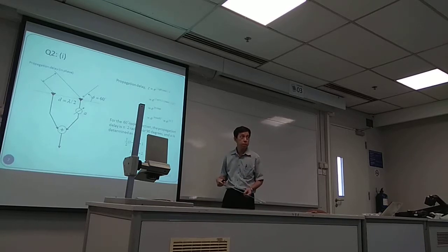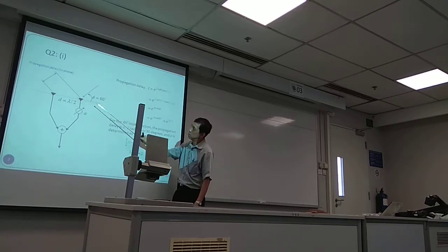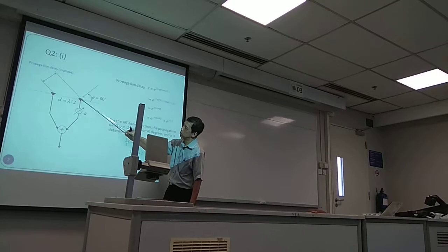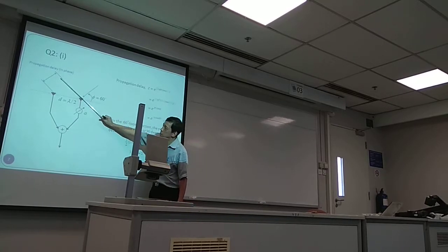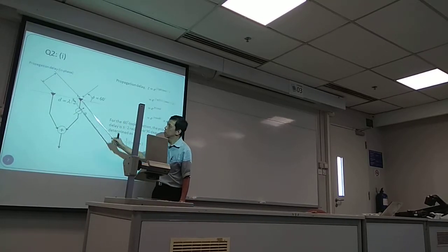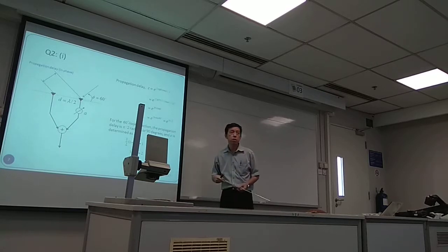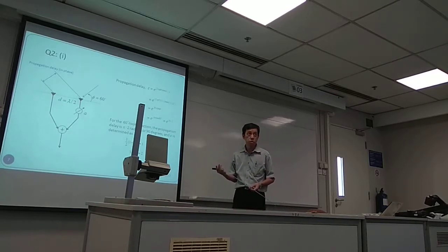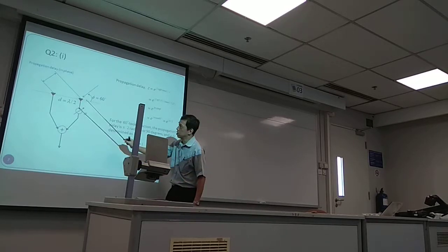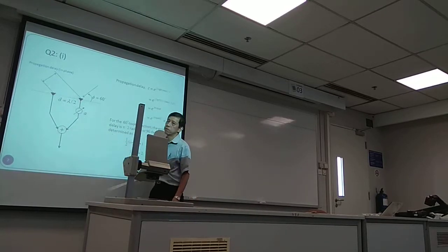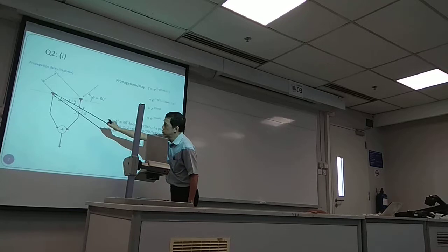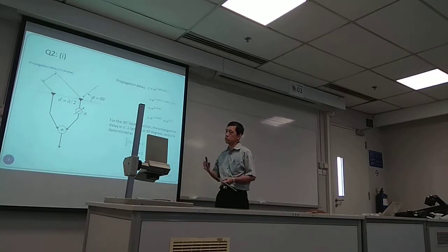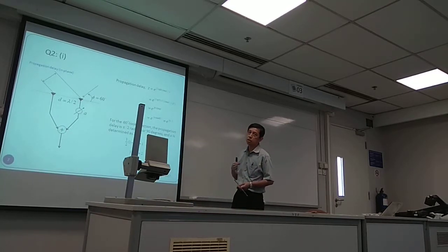of degrees. Okay? So, well, if that's the case, you see that the wavefront at this point may correspond to a certain phase angle. If you take that as a reference, then it will be 0 degree. And then subsequently, while the wavefront will be received by the subsequent element, so the signal will be delayed by a certain amount.